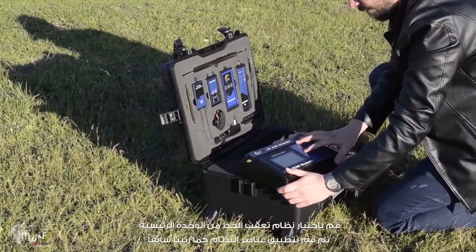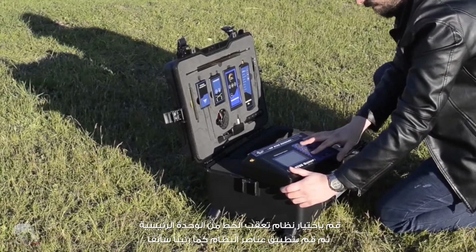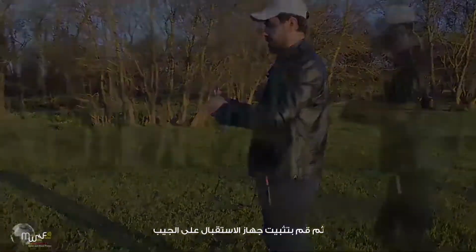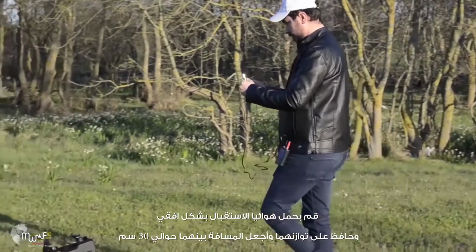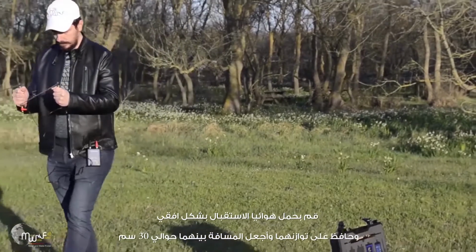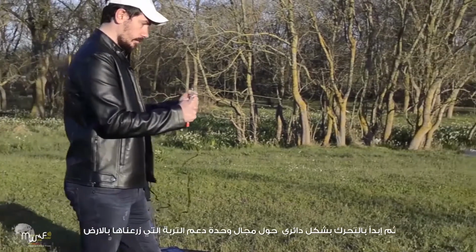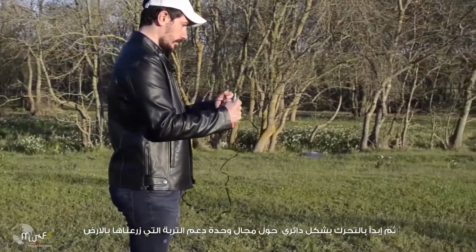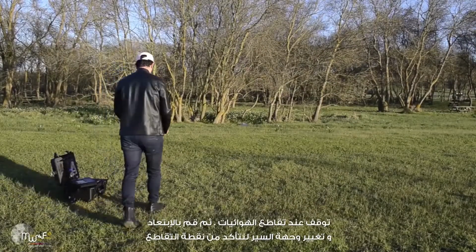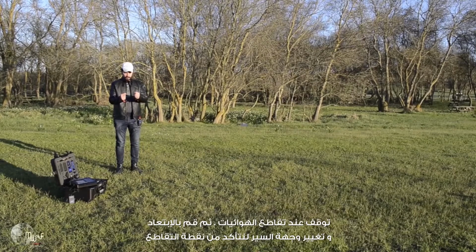Choose the line tracker system from the main unit and assemble the contents of the system as we saw earlier. Then install the receiver on the belt or put it in the pocket. Hold the antennas horizontally, maintaining their balance and spacing between them about 30 cm. Then start walking circularly around the field of the ground transmitter unit that is planted on the ground. Stop at the intersection of the antennas, then move away and change the direction of walking to make sure of the cross point,